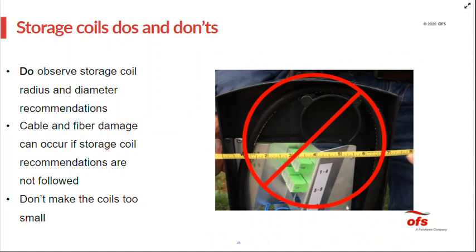This photograph's a little bit dark, but let me just explain what's going on here. So this is a small fiber to the home pedestal. The inside dimension of the pedestal was about 7 inches. And the installer actually stored cable loops inside that pedestal. So the diameter of the storage loops was at most 7 inches.